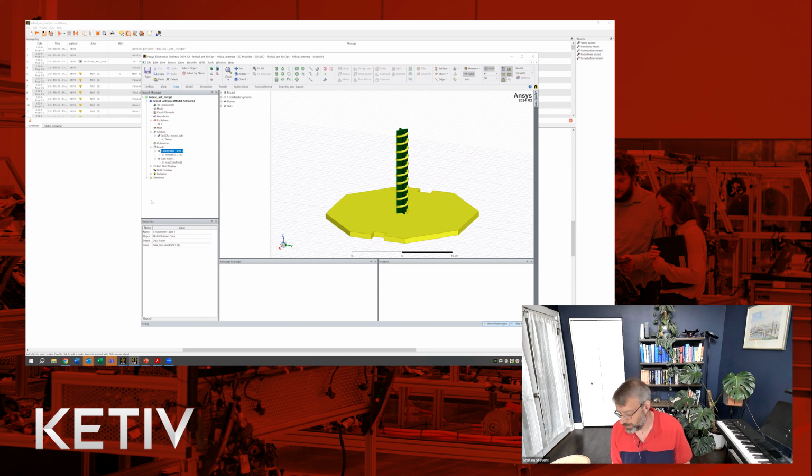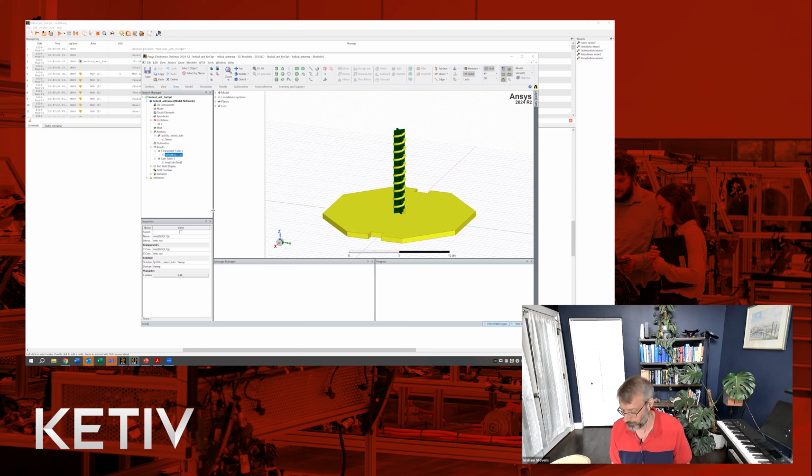And that sets up an Excel spreadsheet right in the same directory that this model is in, which Optislang then uses as sort of the input for its analysis. And when you go through the Optislang setup, it will create some routines that automatically create those tables and grab them for these analyses. So that's the setup of a reduced computation model.